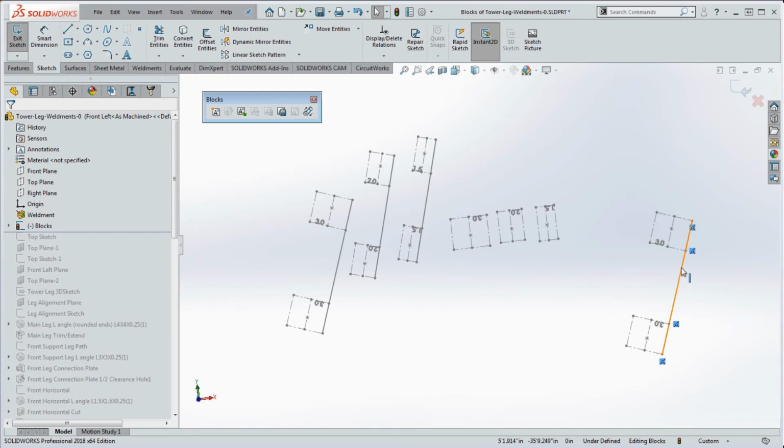Some sort of sketch relation in here for that pass segment line with the 3D sketch line that we have in the background. Or if it's like one of those diagonals, all you have to do is plant these points in there and you have that in place. Then you have this defined in the very top. So once you get these 3 elements defined on the bottom, or 2 elements on the bottom, the third element we're going to define is this one. And just typically 1 dimension after that, like between this point, maybe some other structure that might already be existing in our model, that'll get that fully defined.